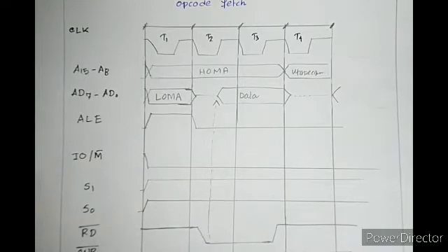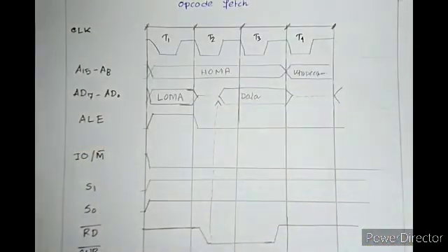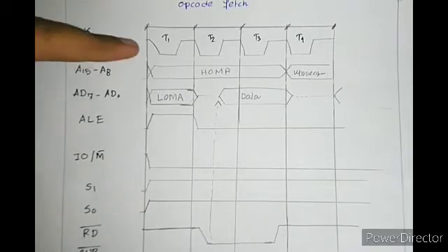Now let's draw some machine cycles. So the first one is opcode fetch. How many T states are required for opcode fetch? 4. So first start from this clock: T1, T2, T3, T4. And I think, as of now, you obviously know that in 8085 the clock pulses work at 50% duty cycle.